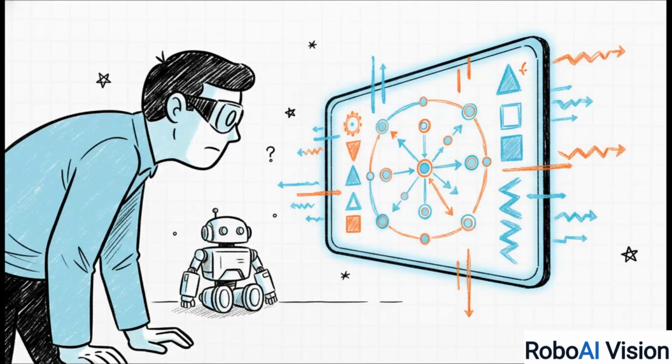Now, as a real engineer, you don't just stare at the physical robot hoping it works. You have to inspect the matrix. Jump into your terminal. If you type ros2 topic echo /cmd_vel, you can literally watch the math updating in real time as the robot turns. Or, even better, run rqt_graph. It automatically generates a live visual map of every single node and topic running on your system. This is how you actually debug and master ROS2. By making these invisible data streams visible.